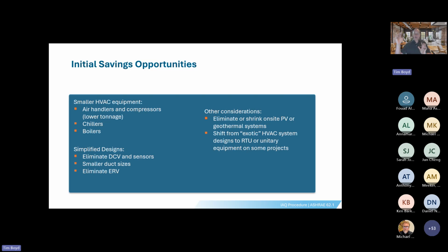Our rep went in and said, no, you don't need to do that. We can actually clean the air and keep your existing ductwork. And so we saved them tens of thousands of dollars on that job. We also saved the architect from having to redesign the spaces, and we gave the school back all that additional square footage. It's a win-win-win on all categories, right? That's fundamentally what you can do here with the right approach to when to use the indoor air quality procedure.